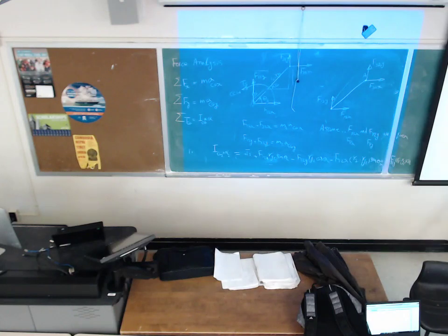And Y of center of gravity would be A sine of theta 2. If I'm looking for displacement and velocity, I differentiate once. Negative A theta dot 2 sine of theta 2, and y dot of center of gravity would be A theta dot 2 cosine of theta 2.